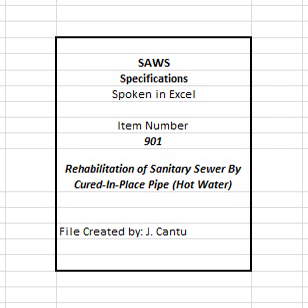D. The outside layer of the tube, before wet out, shall be coated with an impermeable, flexible membrane that will contain the resin and facilitate monitoring of resin saturation during the resin impregnation, wet out, procedure. E. The tube shall be homogeneous across the entire wall thickness containing no intermediate or encapsulated elastomeric layers. No material shall be included in the tube that may cause delamination in the cured CIPP. No dry or unsaturated layers shall be evident.